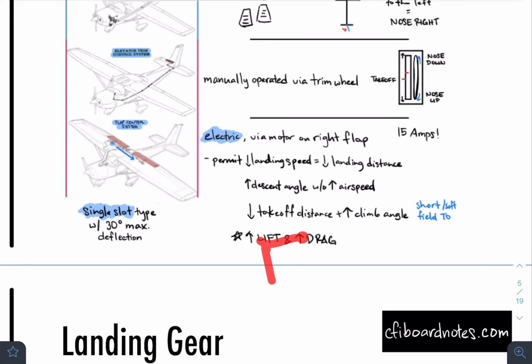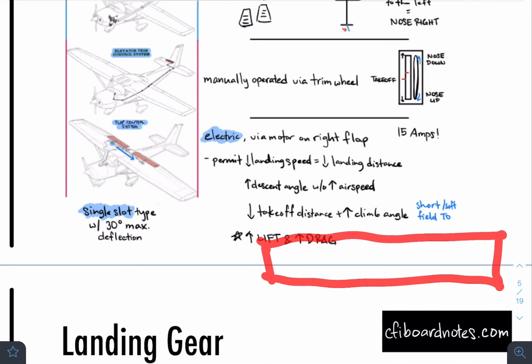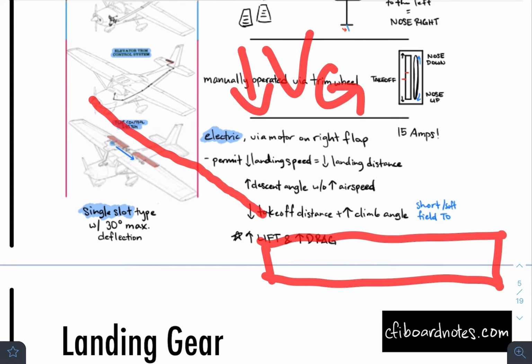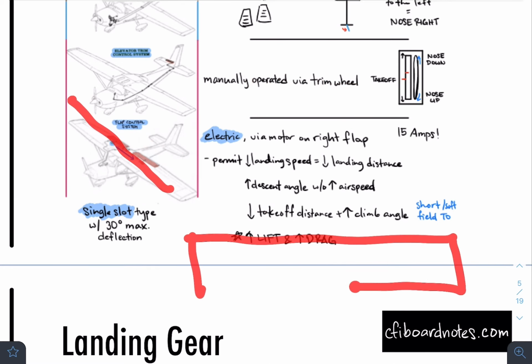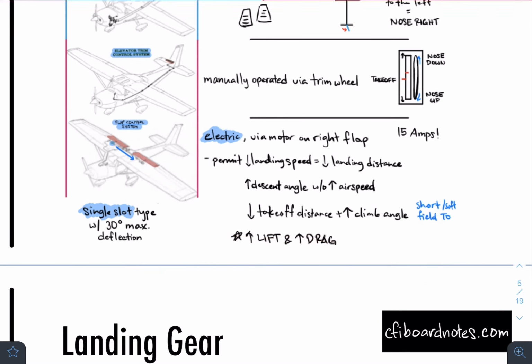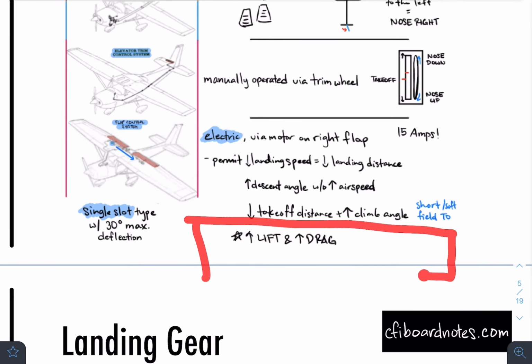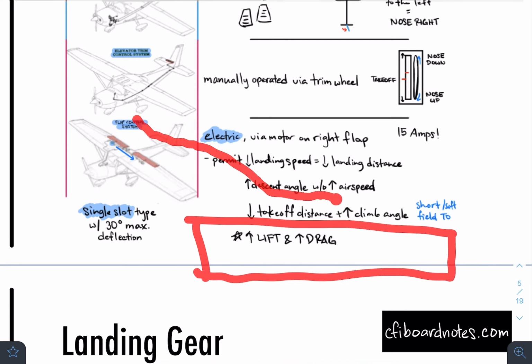For example, this is going to be the runway. The more stable your speed is, assuming you're not below VG or below the landing speed, that allows you to have relatively less float. If you're going faster, once you start rolling out here or leveling off, you might land here. But if you're going at a relatively slower speed, you might actually reach your point, which is going to be in this area.